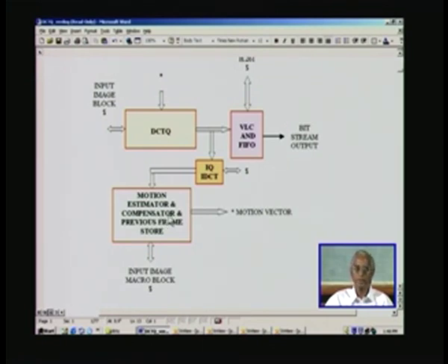So, we take a macro block as mentioned earlier in the current frame and look for the shift in the previous frame, and that is what this algorithm does. Finally, it will create what is known as a motion vector, which will say it has moved by such and such place. The xy coordinate will be transmitted, using which the receiving end can easily reconstruct that motion, and there will be no need for sending the previous frame. We only need to send that particular small macro block where there is a motion change.